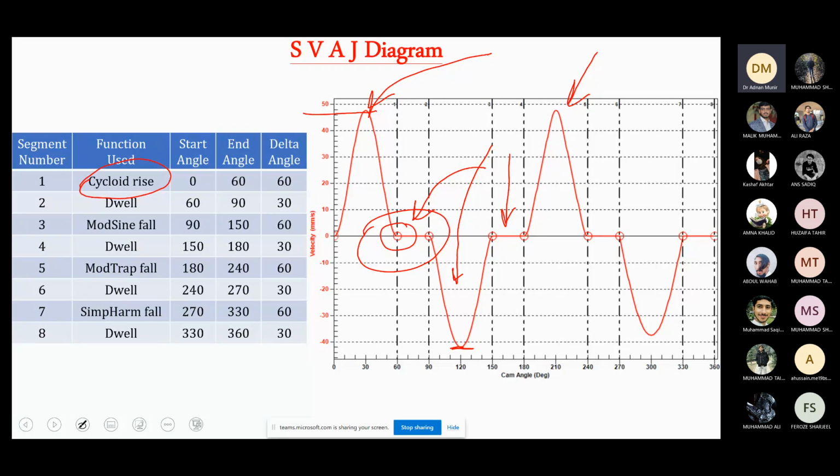very high, then decreases, and then goes very low and decreases. So that will put a lot of wear and tear on the cam follower, right? But again, there is no abrupt change in the velocity. If you look here, the velocity first increases, then decreases and becomes zero over here, and then it remains zero and then increases again. So there is no abrupt change in the velocity, although the peak values are very high, which will put a lot of stress on the cam follower, and it is subject to wear and tear.